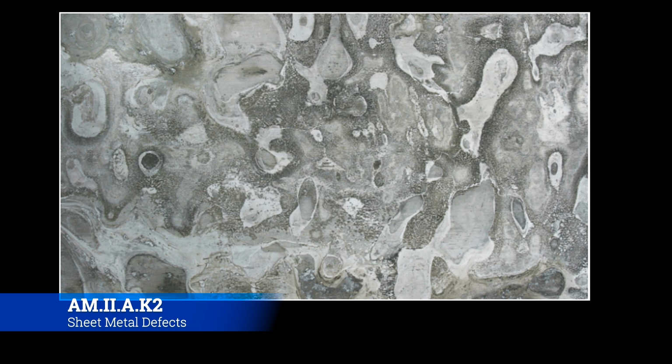However, at your shop or at work, you can easily see corrosion start to build up. You want to be really cognizant of the way you store excess sheet metal for future projects, and you want to make sure that before you install any metal on the aircraft you're using for repairs, you screen it for corrosion, because the last thing you want to do is put a problem on an airplane. You want to stop the problems rather than do that.